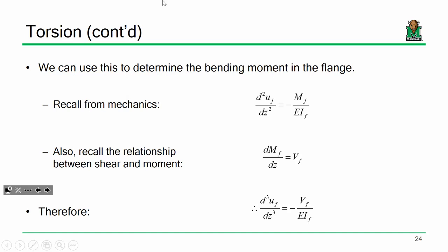This is a very fundamental differential equation. If there's any one differential equation you remember from undergrad, it should be that one, that the second derivative of deflection is M over EI. In other words, once you get your moment, remember you can integrate it twice and there's your deflection. Y'all remember that? Okay, so that is a very fundamental differential equation. This is another one. You might not remember this, but you definitely have used this when you drew shear and moment diagrams. I mean, remember how you draw a moment diagram? You get the shear, you integrate it, a line to a parabola, so the moment diagram goes like that.